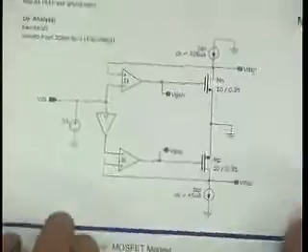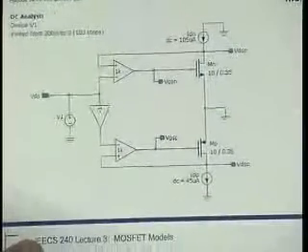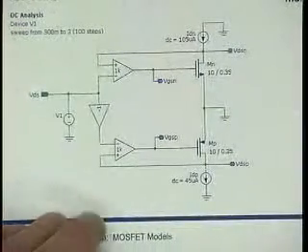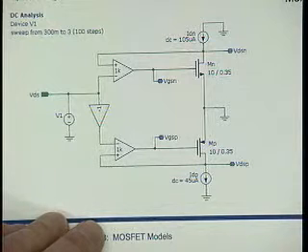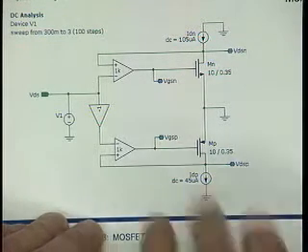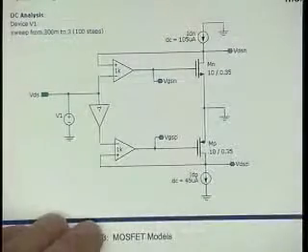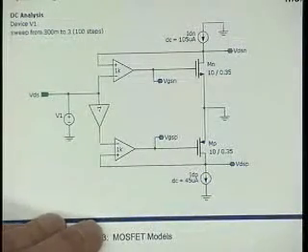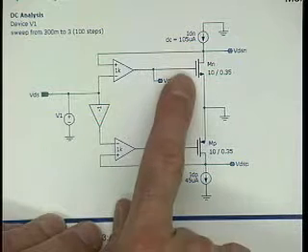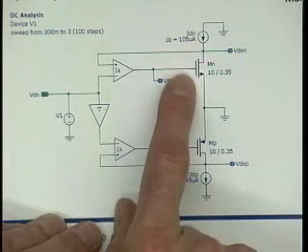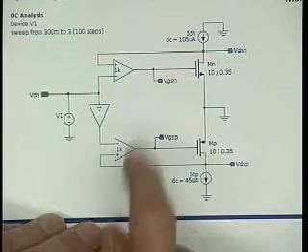And again, I've shown here the circuit on how to extract that. It's not always trivial to figure out something like the open loop gain. In SPICE we have to bias the thing, right? And sometimes what helps, and what I'm doing here, is I actually use a feedback loop. I do not try to set the right VGS, but I'm actually using a feedback loop to set the VGS.